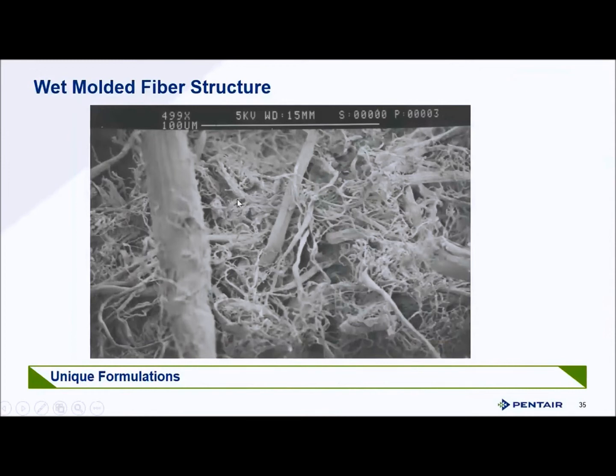But this tortured path, the water has to basically climb over this material, and it's forced to have more contact with the carbon than it would through a similar density pure carbon block. It's kind of hard to imagine that you get more time. It's about taking residential streets versus the highway is really what you have going on here. Lots of turns, lots of rights and lefts going through here, making sure we're hitting that carbon.